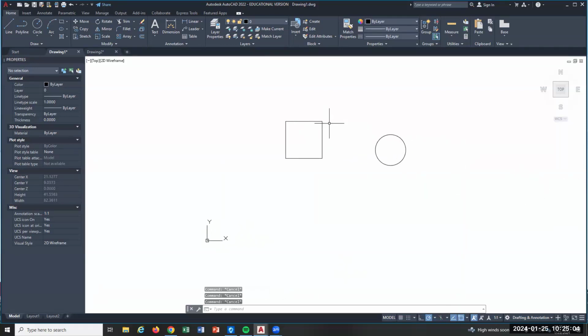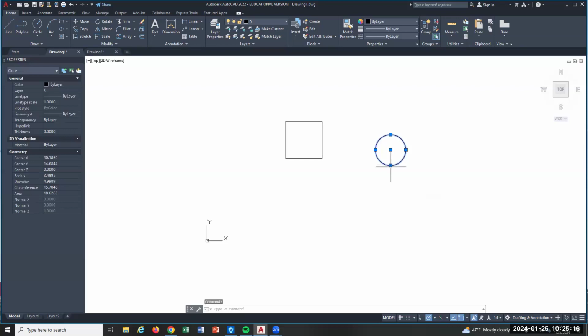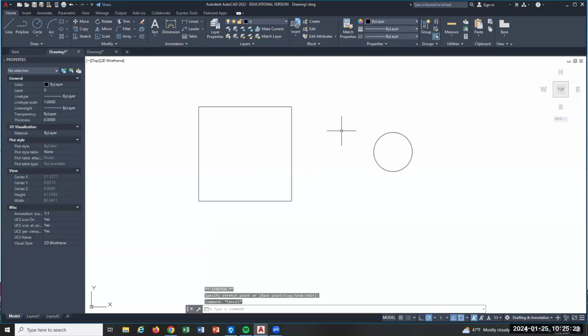All right. Hidden lines, last thing, and then I'll just let you start wrestling with this stuff, okay? The easiest way to do hidden lines, let's say that I had my circle here. I'll change its size a little bit, and maybe change its position. Like that's my side view, this is my front view, and I know that I have to have these projections over here. I'm just going to use construction lines to put them in.